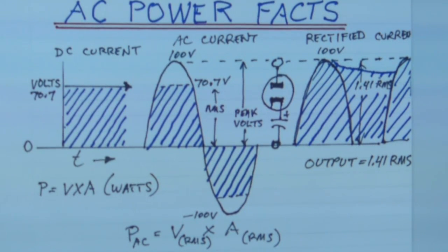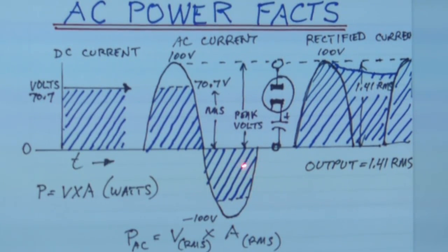So if I can do my little pointer. I've purposely chosen the voltage here at 70.7 volts because the equivalent AC is going to come up to a peak of 100 volts. Now AC stands for, of course, alternating current, and the waveform is considered a sinusoidal waveform, or sine for short, because that's the mathematical function associated with that wave type.